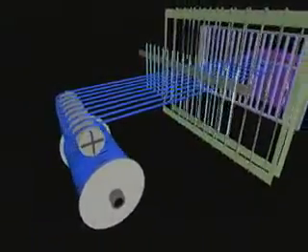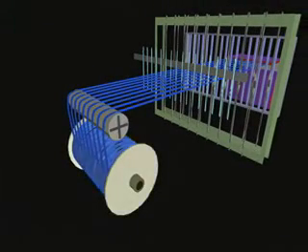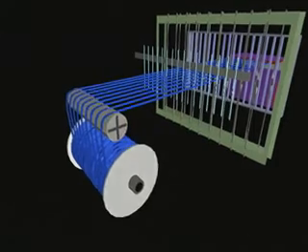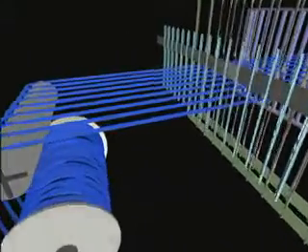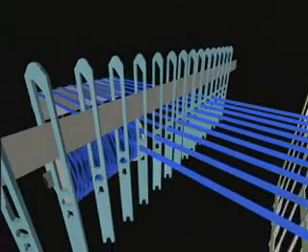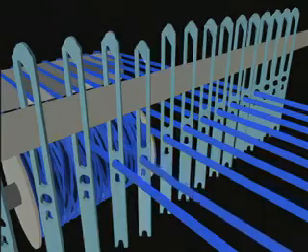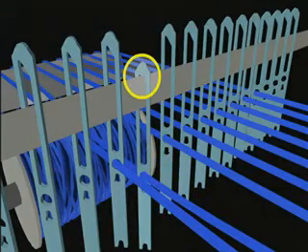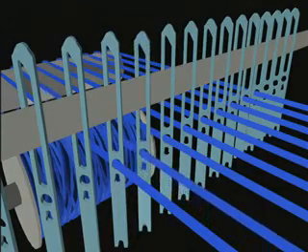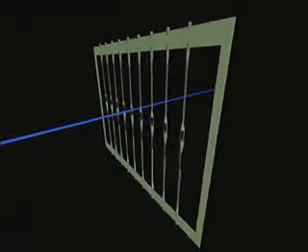The weaving process starts with the sized yarn coming off the loom beam in a single sheet or layer of yarn. The yarn then proceeds over a tension or whip roll that is designed to maintain a constant level of tension on the warp yarns throughout the entire weaving cycle. Each yarn then travels through its own drop wire that serves as a stop-motion detector. When yarn tension drops too low, or when the yarn breaks, the metal drop wire will complete an electric circuit and the loom will stop.